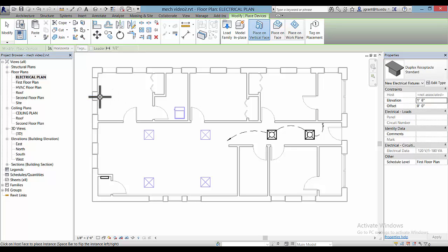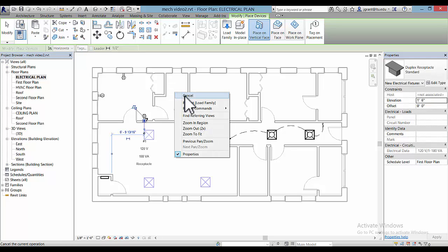Here we can place a standard receptacle on any wall that's bigger than 2 feet, and there's a standard code that says that they need to be 12 feet apart, or at least have a spot anywhere that can reach within the 6 feet. And sometimes that code changes, but not very often. In these smaller rooms, we'll just put one on each wall. Let's take a look at